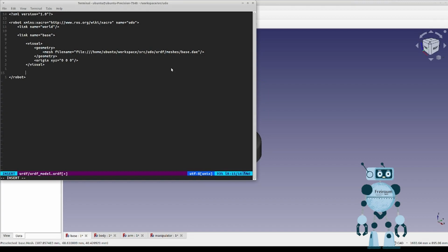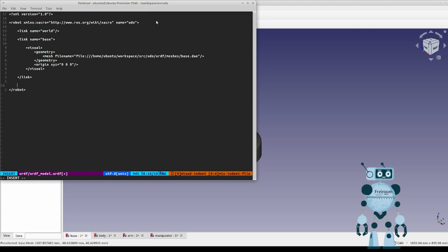We defined the first two links, the world link and the base link. Those parts have been created using a CAD program and now they must be joined together. Let's call this joint ODM. Let's define it as of type fixed because we want to connect the lower part of the robot with the world statically. We need to define the parent link, world, and the child link, base. Basically, we are telling ROS that we want to weld those bodies together, with no rotation or movement between them.